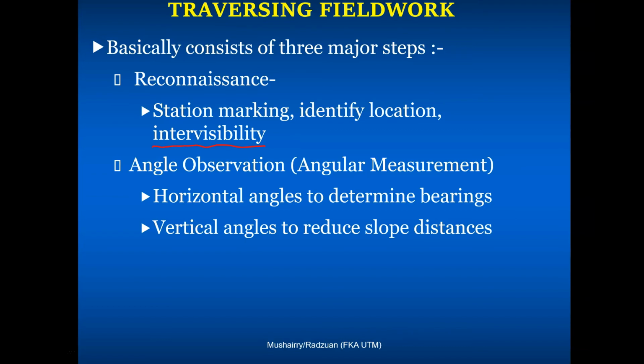So most highly likely, the distance that you measure will be a slope distance. So you need to know what the vertical angle is so that you can get the horizontal distance, because that is what we want when we do our calculation.